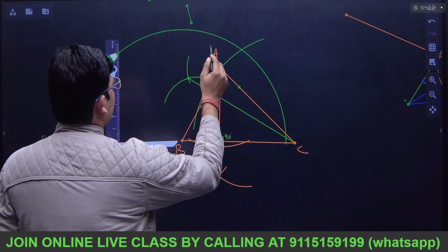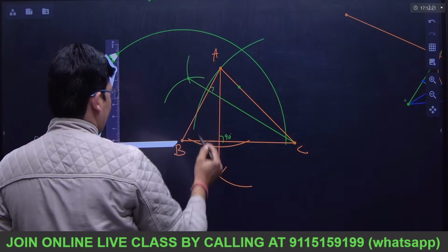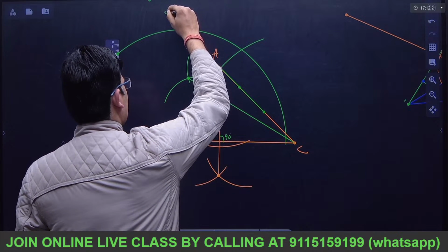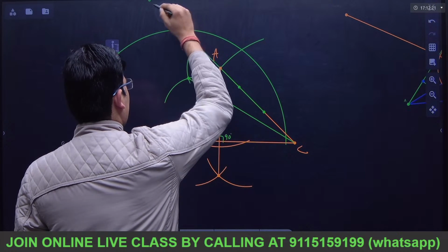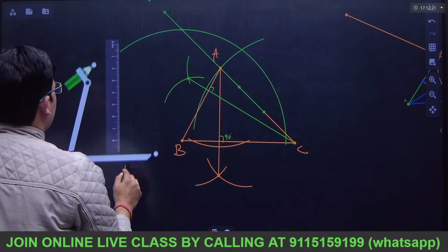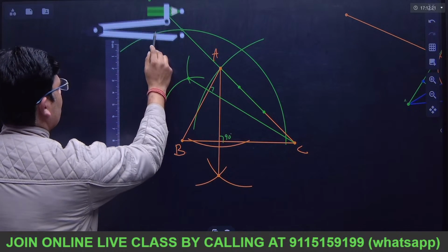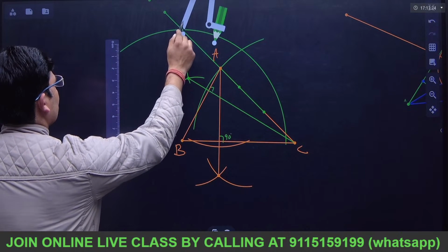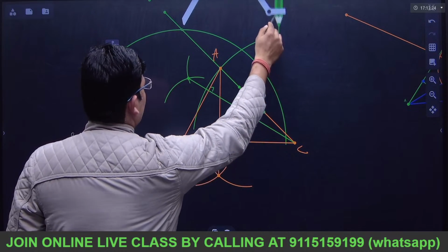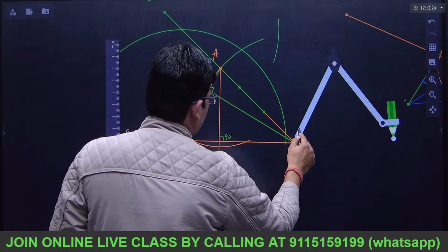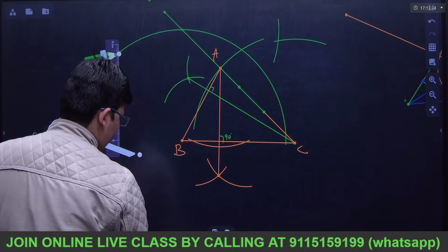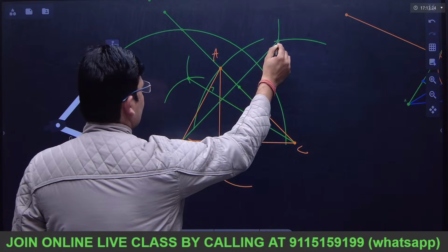See, the perpendicular is not going to be made on the line. So the line has to be extended. So I have extended the line, and this is the point of intersection. Now to draw a 90-degree line, I have to take half of it, draw one arc, then from here again draw another arc. So now this is going to join with this.